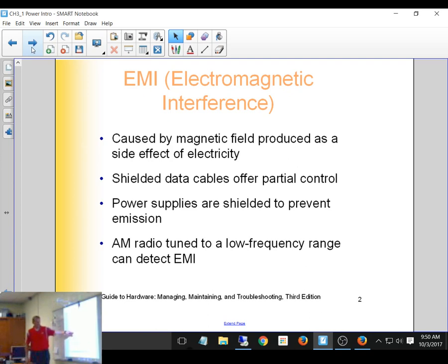If you get better cables, it offers partial control. The best thing you can do is not put things really close. So we'd end up going up through the rafters, over the lights, so the cables wouldn't be laying right on top of them, and then come down to the projector, and it would solve a lot of the problem.